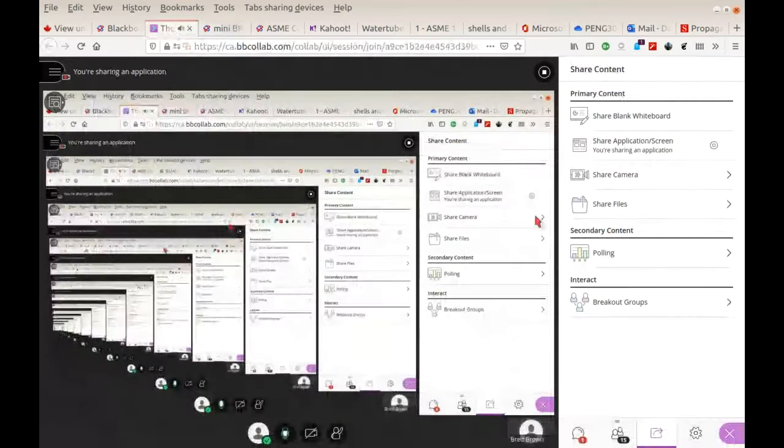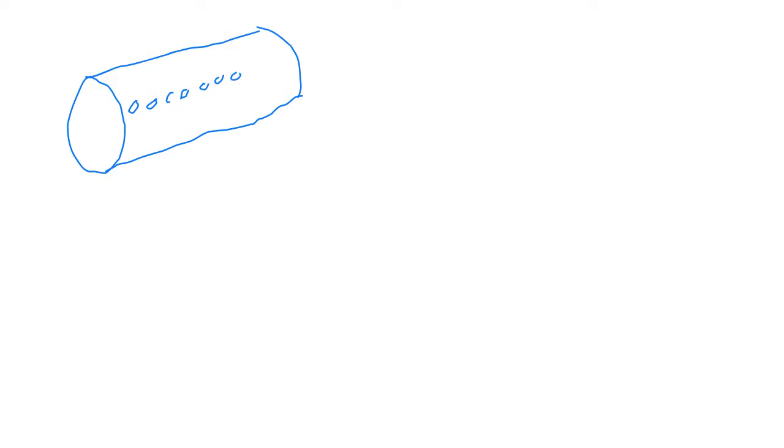So let's very briefly talk about ligaments, exactly what is meant by these ligament thingies, okay? So we are going to do some drawing, and here's a steam drum. Or, I'm going to make it a mud drum because it'd be easier for me to show. I've got a whole bunch of tubes attached to the top of it. So what I have is a regular pattern of holes. And what I have done then is, along that plane, I've got less material to oppose the circumferential stress.